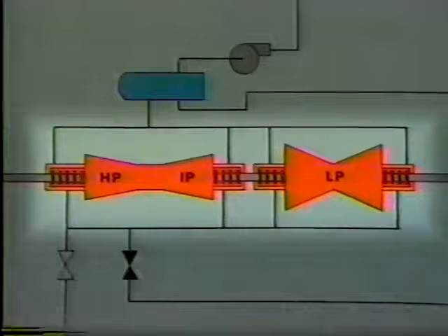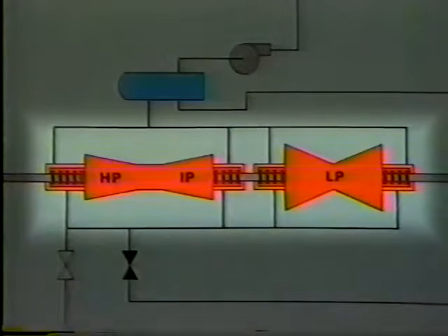As steam pressure inside the turbine increases, steam starts to flow out of the high pressure and intermediate pressure sections into the seals. The steam flows past the first gland. A small portion of this steam travels through the second gland and into the gland seal exhauster header. However, the majority of the steam flows into the gland seal supply header.